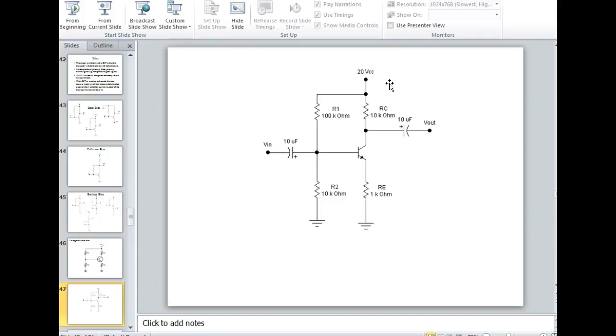Over here, what DC component does AC have? Let's go back. What's the DC average of an AC cycle? Huh? 0. So that means this is considered to be DC 0, right, or ground. So DC sees an AC source as a ground. So this is, well, I forgot about 2 volts. So that means this is positive relative to the AC input because true AC is considered to have a 0 volt reference, right? Y'all understand?